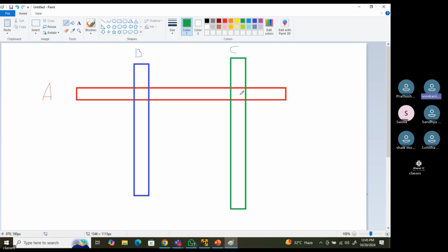Can you repeat, sir? I am telling you, if the signals are different but you are routing with the same metal and those metals are overlapping each other, it will for sure give a short. You need a different metal to route there. Now if you want to connect both the signals, you have to put a via there.